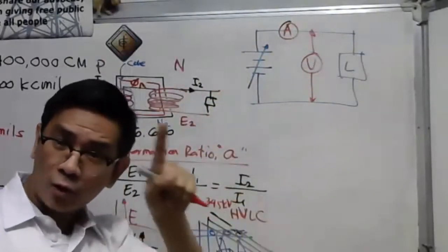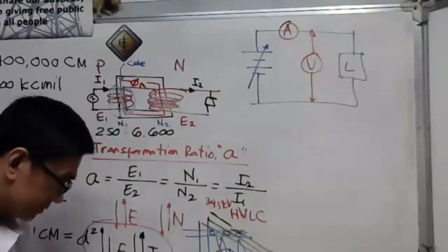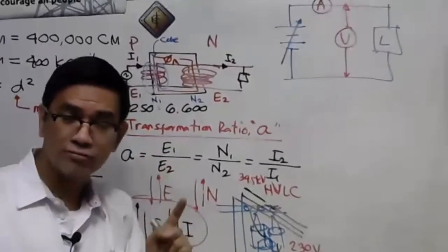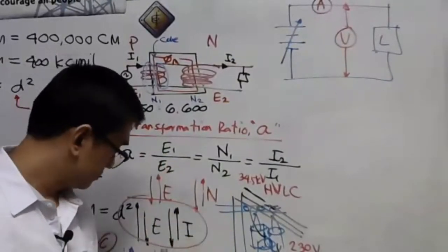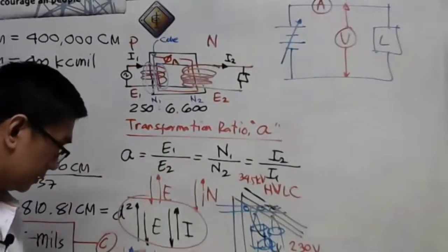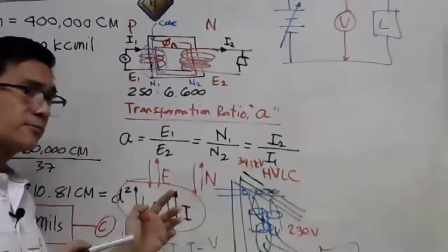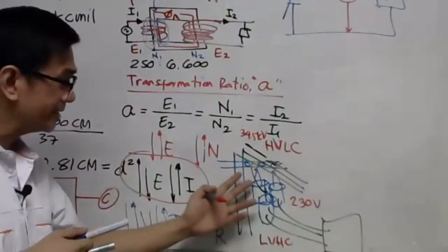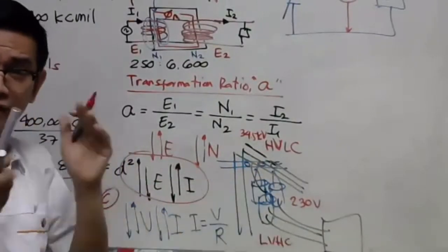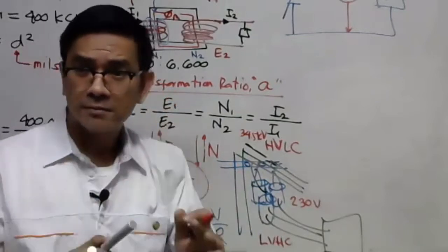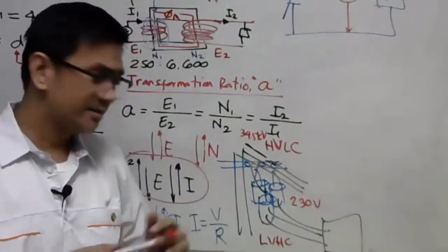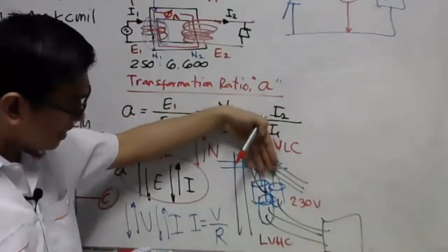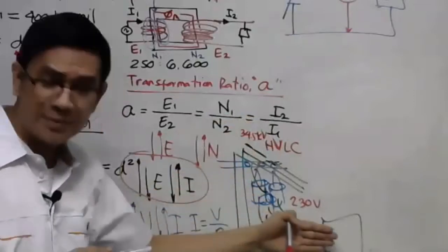But if you are going to use a transformer, that will be in between your source and the load. It's a different thing. You have to consider the transformation function of the transformer, because this transforms without changing the power. It doesn't change. If you have a power here, let's say of 300 kVA, this is also 300 kVA on the secondary side.